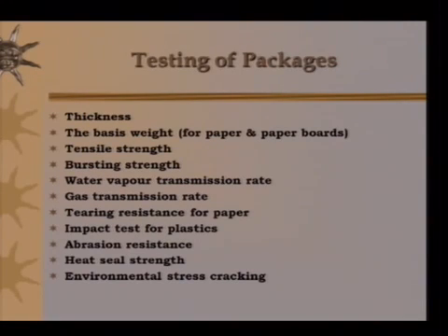And before these go into packaging, there are certain tests which have been performed on the packages, that is thickness, the basis weight, tensile strength, bursting strength, water vapor transmission rate, gas transmission rate, tearing resistance for paper, impact test for plastic, abrasion resistance, heat seal strength, environmental stress cracking.